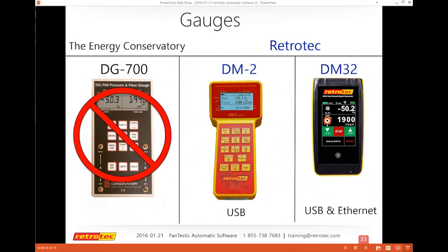And so the DM32, hey Colin, can I get you to mute? Yeah, I just wanted to make a point on one of the questions that was answered by Nigel. He said, do the fans work together to create the overall test pressure within the building? Yes, they do. So if you've got 3 fans on the bottom floor, they all work together to create the pressure. If you've got a fan on the 3rd floor, it works together to create the total pressure. Now, I think the response that was given to this question was a little bit misleading.